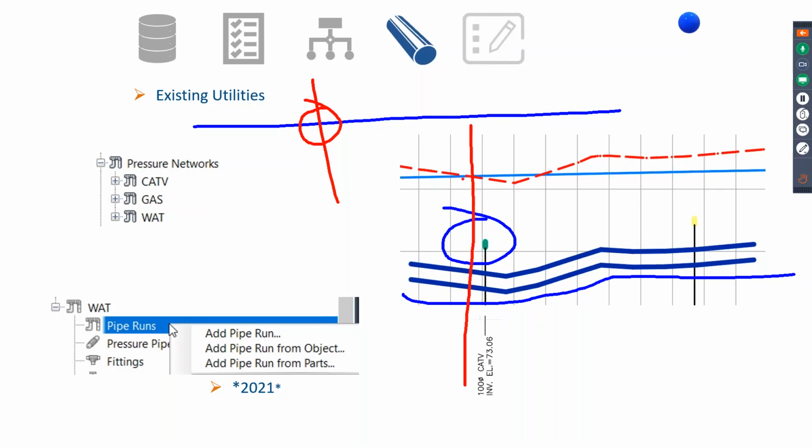Then I have to figure out what elevation it is, about a meter below that. Then I have to insert my block or draw my ellipse. Then in this case, I have to draw a line down to the bottom. I have to label it manually, of course. Calculate the actual elevation. So each one of these things takes time, maybe 2 or 3 minutes, maybe more.